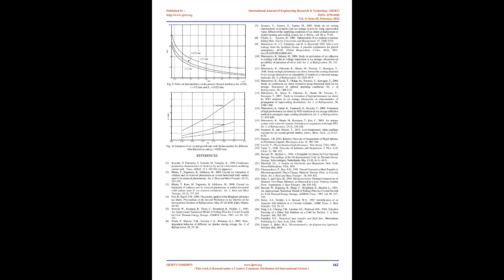V. Conclusions. A numerical simulation of ice crystal growth in the falling films for the laminar case has been performed. As expected, the results showed that the Nusselt number at the wall appears to be primarily a function of film thickness and is essentially independent of Stefan number. The ice crystal growth rate was seen to be primarily a function of the Stefan number and film thickness.